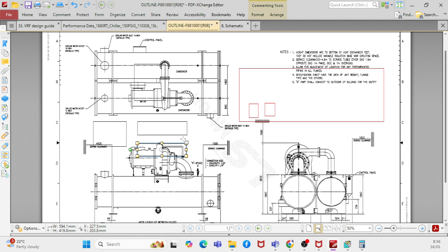Whereas with a water cooled chiller, you are increasing the maintenance, because you have a water cooled chiller, then a cooling tower, then a condenser pump, and then chilled water treatment. An air cooled chiller is a simple system, though the number of chillers is much higher. If you go with a water cooled chiller, the number of components is much higher.